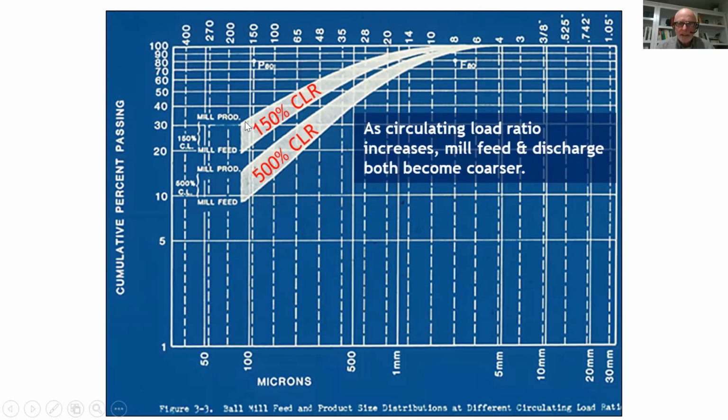And the size distributions going through the ball mill with the much lower circulating load are shown here. It's striking that these size distributions are very different. We can see that the high circulating load mill has much coarser material passing through it. In fact, you can see that about 15% of the material on average in the mill is finer, and 85% of the material is coarser than the P80, compared to about 72% of the material being coarser than the P80 for the low circulating load mill.